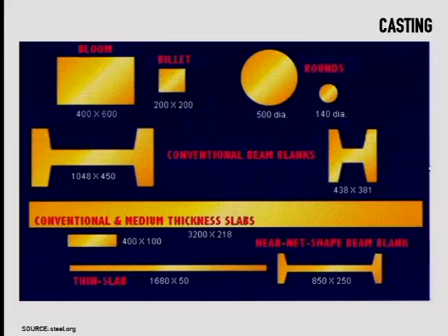But considering that at this stage it's a little bit like concrete, isn't it? We can more or less get all the shapes we want. So why don't we shape it in order to work properly, in order to work well under specific load conditions? For instance, we know that generally tensional stresses tend to be higher in the top and bottom parts of beams, and the web is generally something that we can make lighter. So why don't we shape it, for instance, in this way?